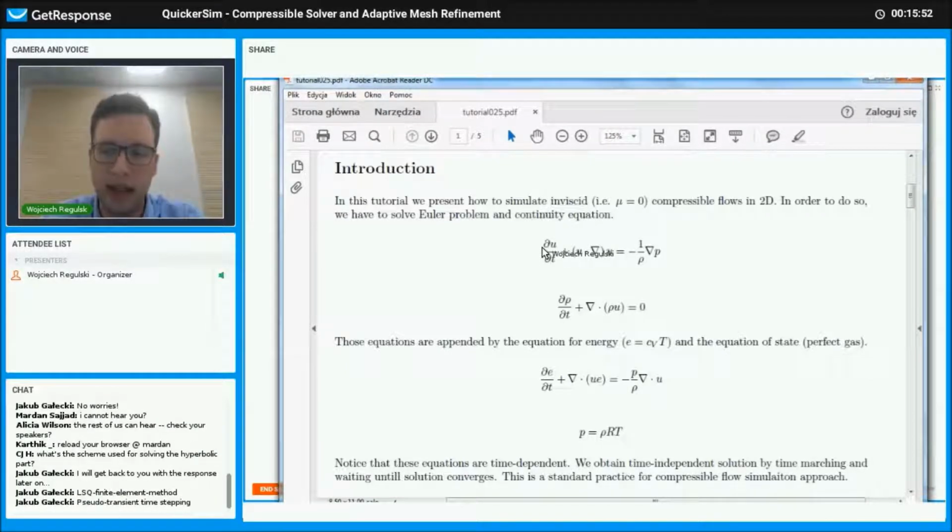So essentially what we're going to do is step in pseudo time, meaning we're going to be calculating a not all that accurate transient solution until the simulation converges to a steady state. So until the change in the simulation from iteration to iteration is fairly small.